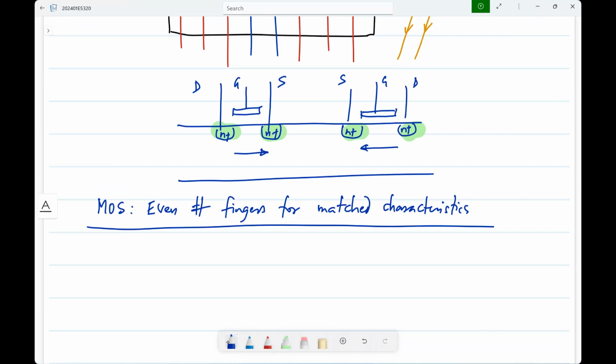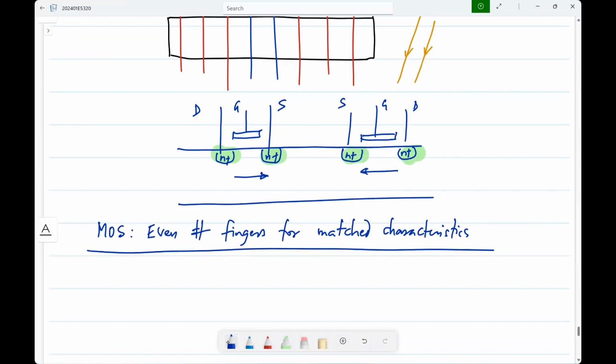Now let's say you fix all the systematic mismatch, which essentially amounts to, you can even say, carelessness. That is, you didn't make everything identical, that's why it was there, but now you know how to do it. You make everything unit element based. Everything should be fine. But even then, it turns out that if you make, let's say, 1,000 identical units, I'll use the resistor example, but the same holds for everything.